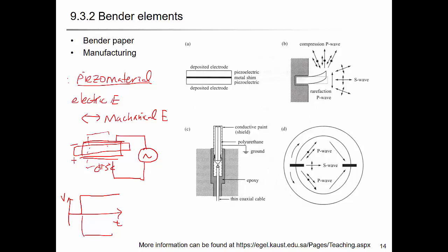And so this bender element is you sandwich two piezo crystals, and you apply the voltage, and the one will expand. For example, this is grounded, and there's a voltage plus. Then this will expand, right? While this is fixed, and because there's attachment between the upper piezo crystal and the lower crystal, this is going to bend in this direction. That's how it works.